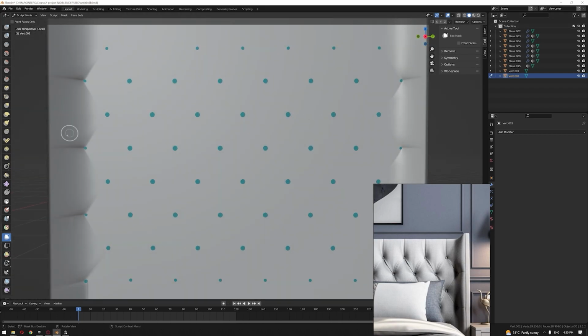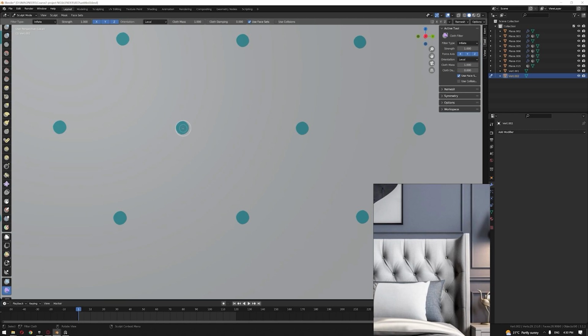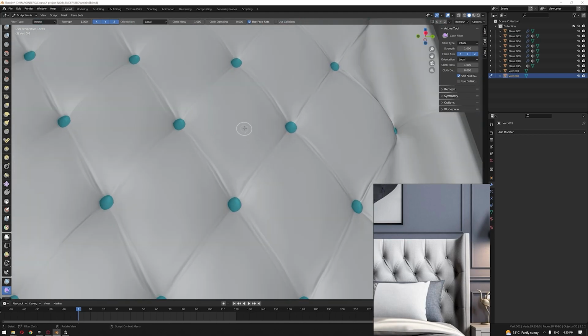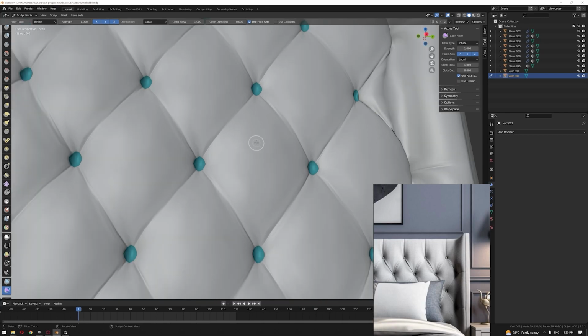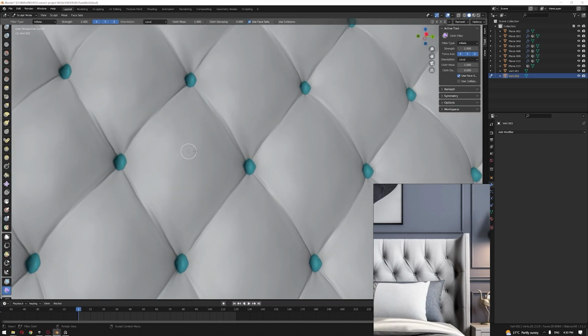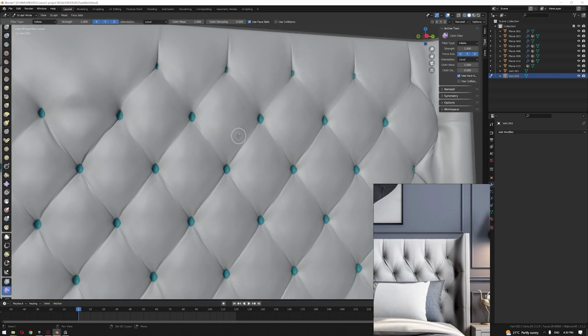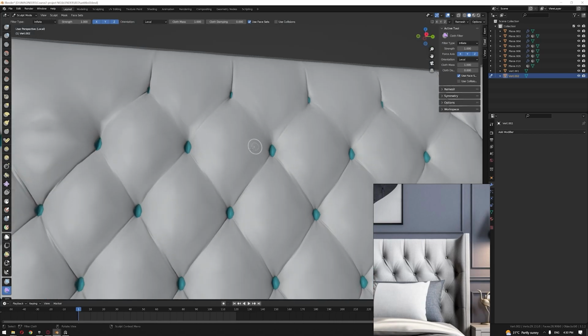Now we'll go to the brush or the cloth filter inside the tool, inflate, and make sure you select use face set. Then we're gonna go inside and then drag from here just a little bit to the left and add another drag by a little amount, another more, and another more. The smaller drag you are doing, the more details you're gonna get. So this is roughly coming up okay as far as I think, just for this area, maybe because the segments was too much. But the more you're gonna add, it will give you more details.